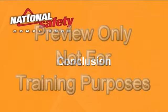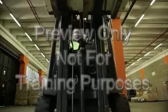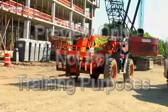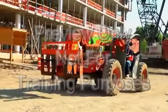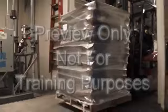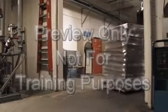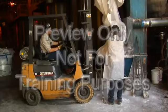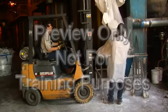Conclusion. Operating a forklift is an important job in most industries. Always know the type of truck you are driving and make sure you inspect it before taking the wheel. Never overload your truck or drive too fast for conditions. Be safe while driving the forklift every day, every time.